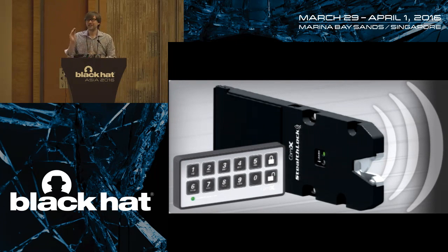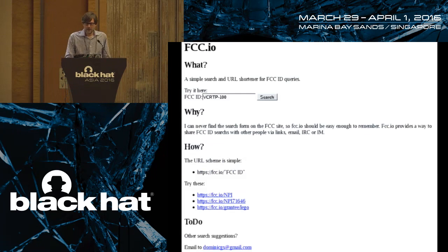When you put the battery in, it doesn't immediately transmit. It doesn't transmit until you enter a PIN and then press the lock or the unlock button. While you enter a number, which is a 4 to 8 digit number, it doesn't actually transmit. But when you push the lock or the unlock button after entering a number, that's when it transmits. So it seemed to be pretty straightforward. When I press the lock, it should be sending that PIN with a lock code. And when I press the unlock button, it should be sending that PIN with an unlock code. And ever since we fixed that, this device has worked just fine.